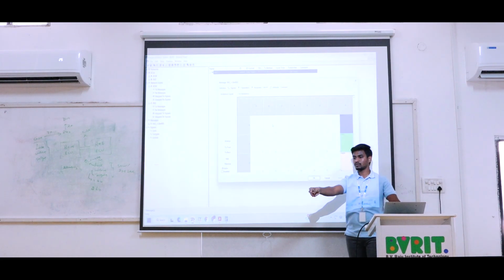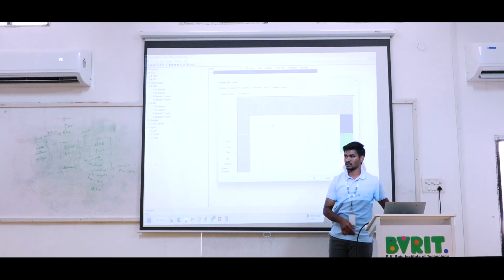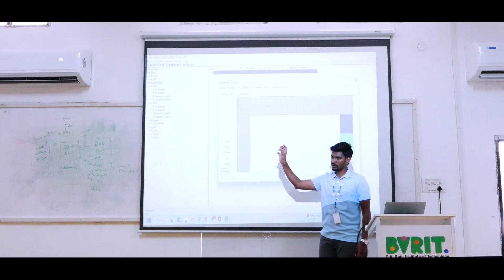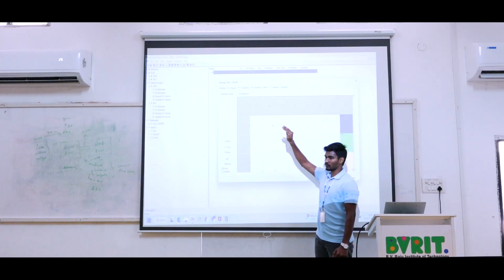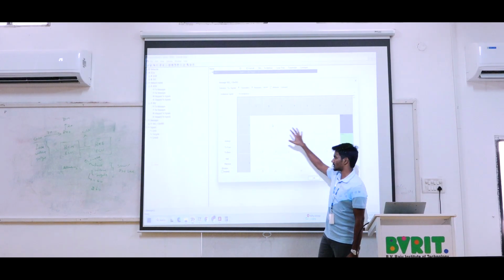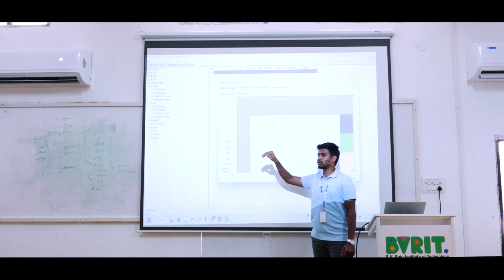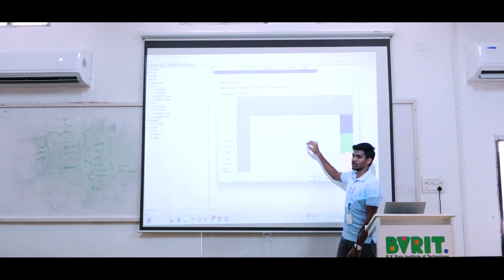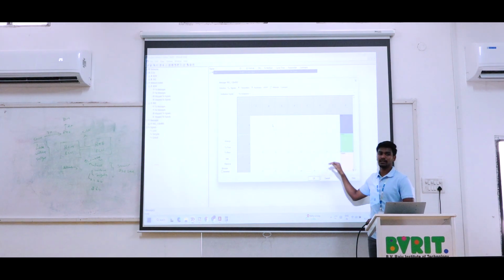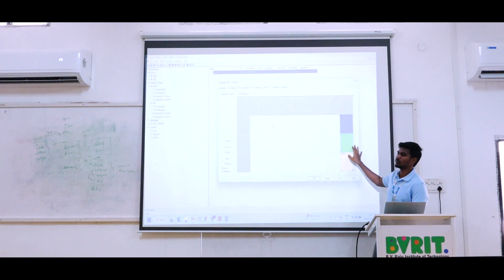So in writing the program for the Arduino on the ECUs, we will create the ID. We are going to use the real-time transmission now. So create ID number 400 and then mention DLC as 3. On the DLC we are using the array concept. So array of 1 is lock, array of 2 is unlock, array of 3 is tail. Now you will not get any confusion. If you work with the real-time concept, you will not get any confusion.